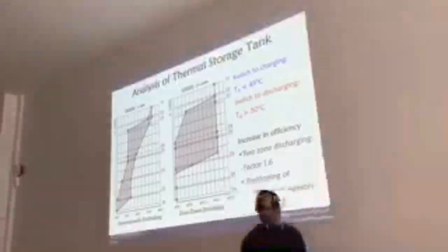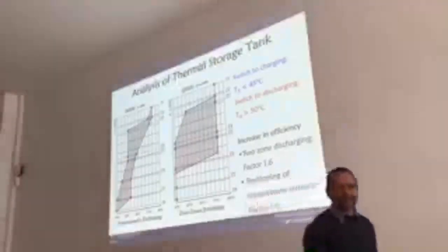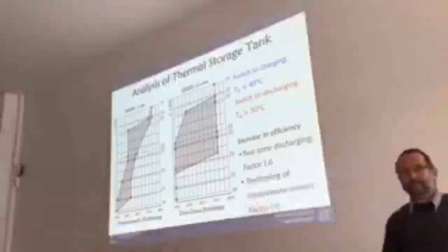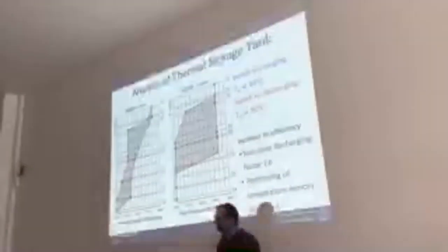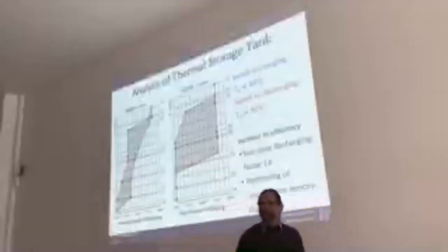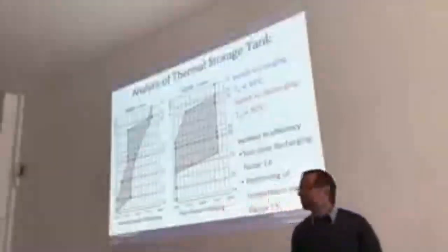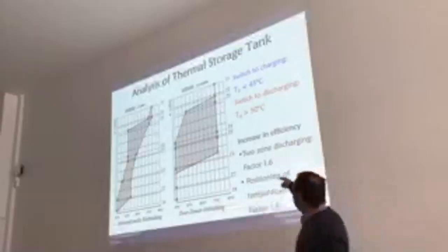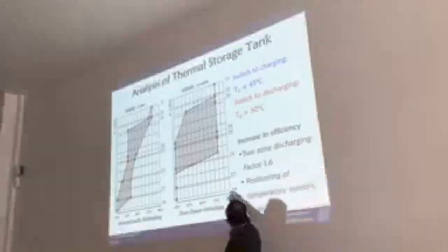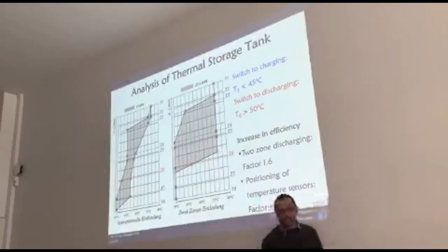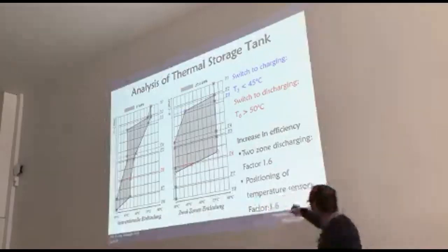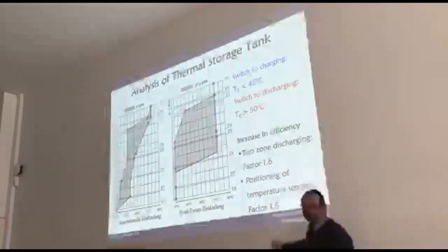Is that the very bottom of the storage tank? Definitely not, and you see it very clearly in that slide. All that lower part here isn't charged at all. So it would be a much better solution putting that sensor T6 to the position T8, and then that line comes down to that part, and that gives you another increase of storage capacity of about 1.5.